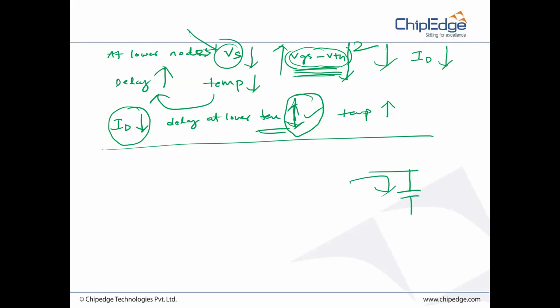More time to charge, less ID. If it takes more time to charge, what happens to delay? It increases. Yes or no? Yes, sir. So that means as ID reduces, delay will increase. Delay will increase. Please understand.